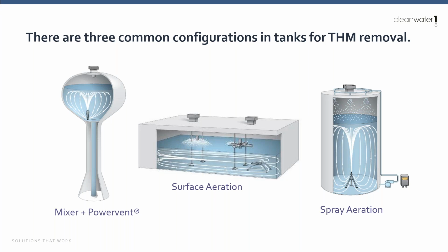And then once you've got these spray aeration systems in, you've got these header pipes up at the top of your tank, and you've got nozzles. And guess what? Those nozzles are going to clog. So if you haven't figured out how to scaffold your tank, get to the nozzles, and unclog them, you're going to have problems over time. And then you've got all this pipe, you've got to coat it. It's really not ideal from a long-term perspective.